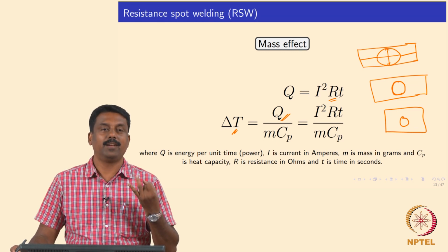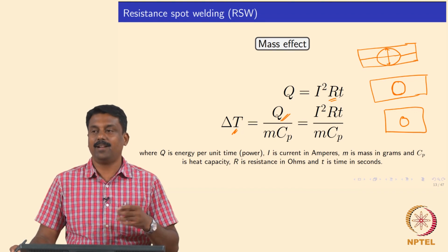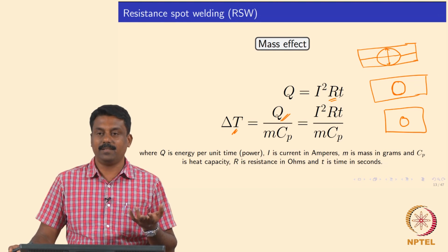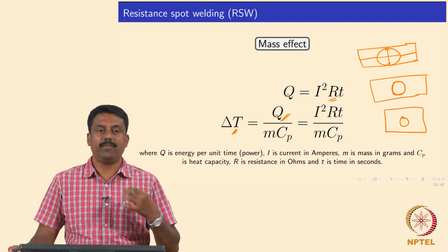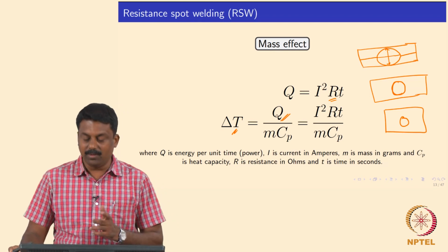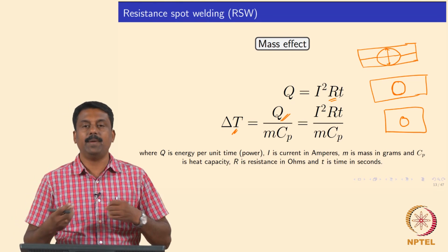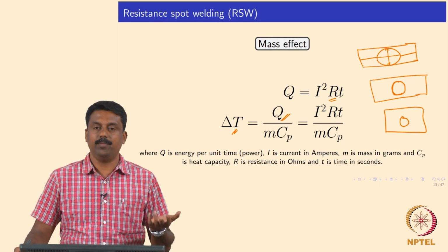Electrode resistance, R2 is the sheet resistance or the base material bulk resistance, R3 is the contact resistance, okay. R4 is the resistance between the interface and the electrode, okay. So once you know the resistances, we always assume the contact resistance is the maximum. Compared to contact resistance, other resistances are negligible.